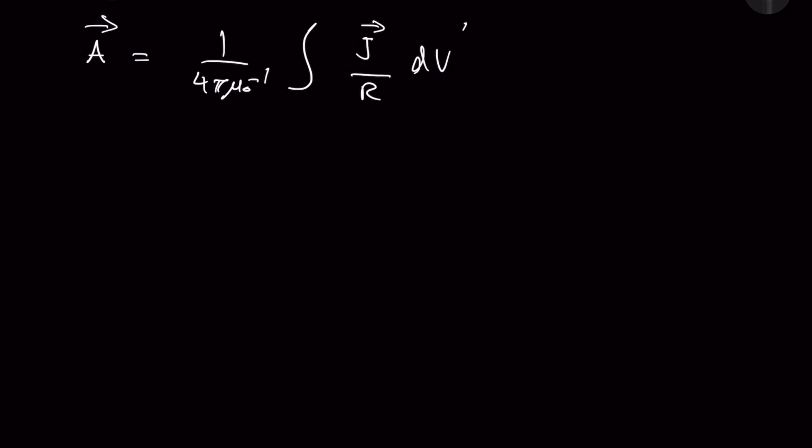All right, now that we have determined how to calculate the vector magnetic potential, we can proceed to calculating the vector potential of a magnetic dipole of a current loop. And the radius of this loop is going to be much smaller than the distance from the center of the loop to the observation point. So let's go ahead and have a look at that.